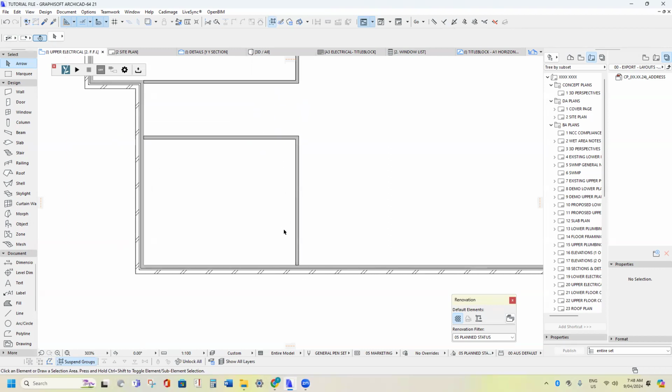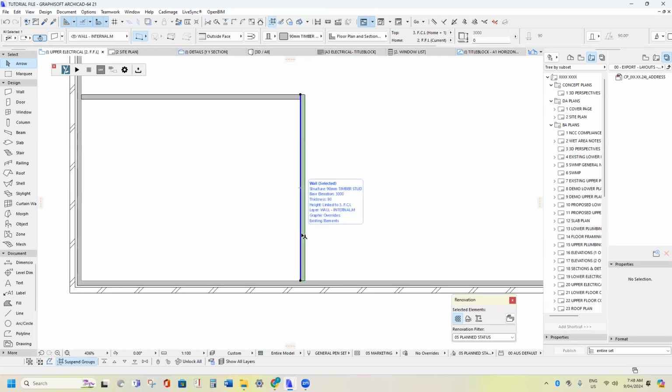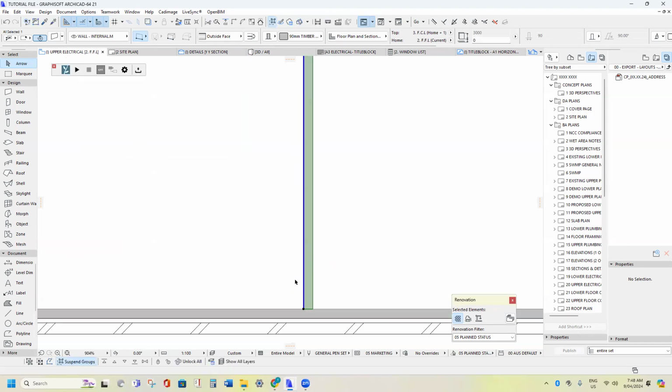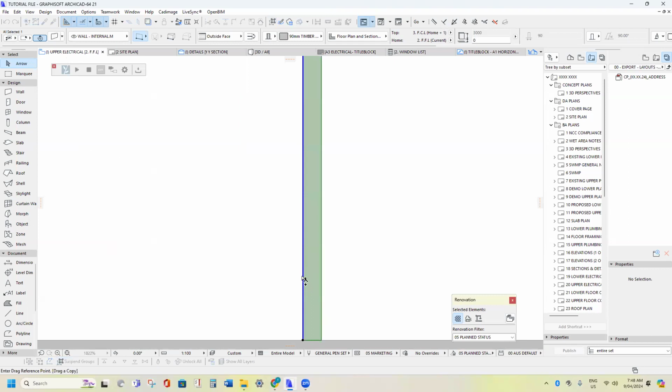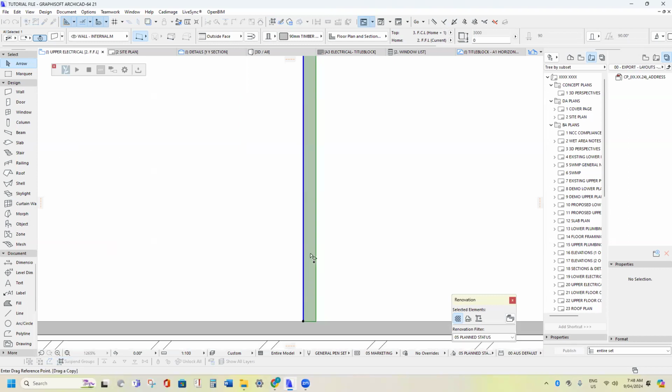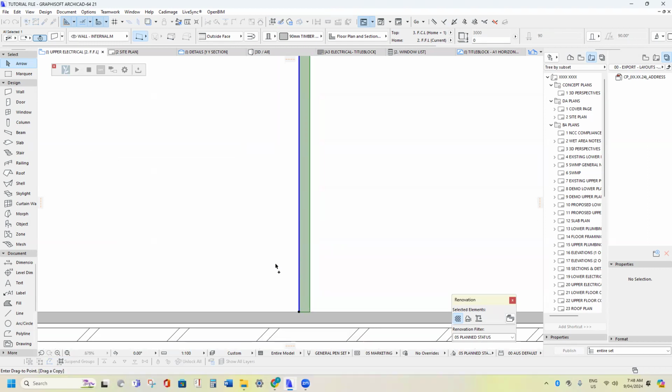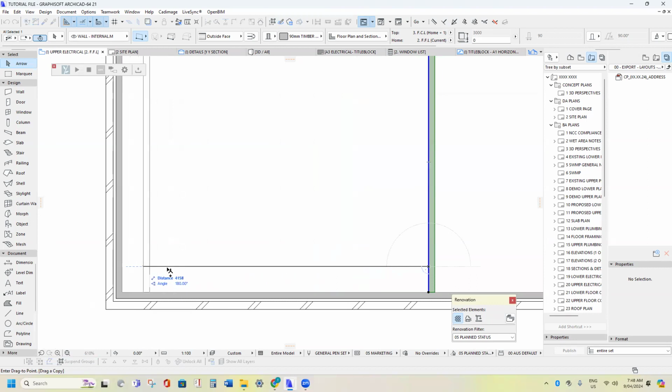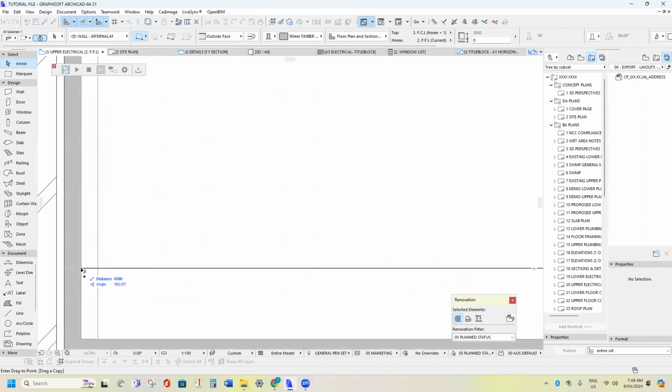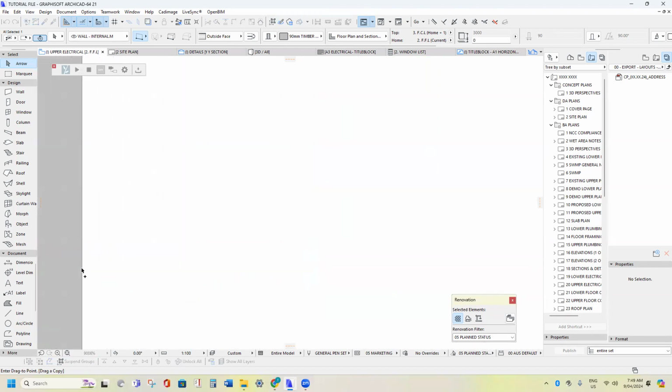Now this size here, I'm going to drag a copy. So I'm going to click on that wall, Control Shift D, and make sure you always click on the blue part there. Don't click somewhere random, because then it's not going to be accurate. You need to click on that part, because that's the part you want to hold Shift and go right. You can zoom in with your center zoom button.